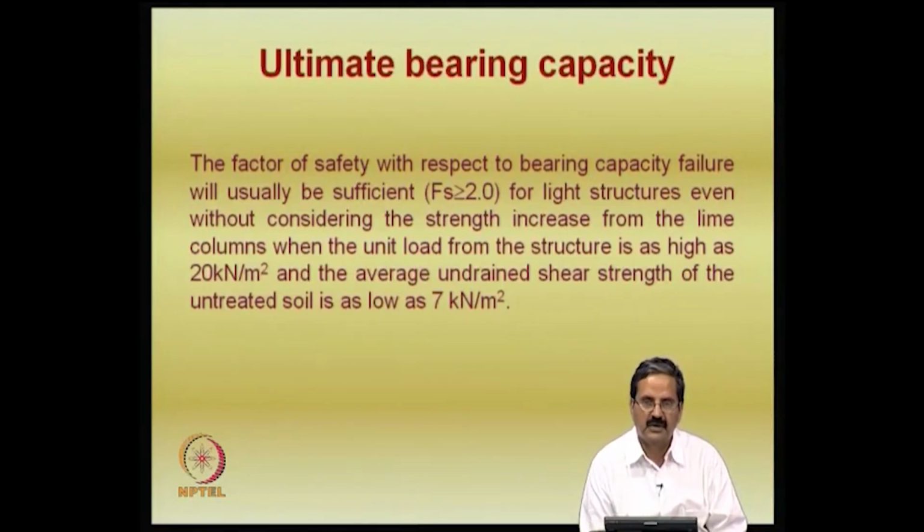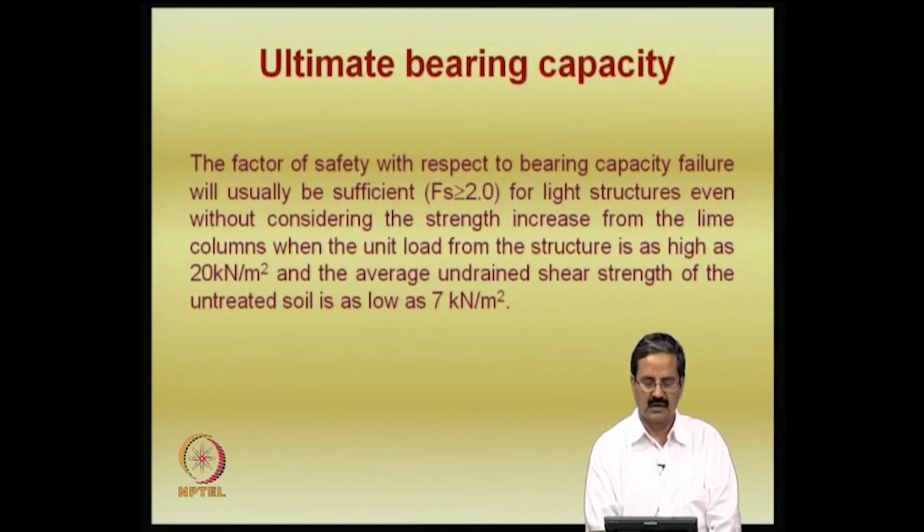The unconfined compression strength divided by 2 will give you the C value, is it not? So, you will get a C value and then use 5.14 Cu as the ultimate bearing capacity, and you treat that as clay.